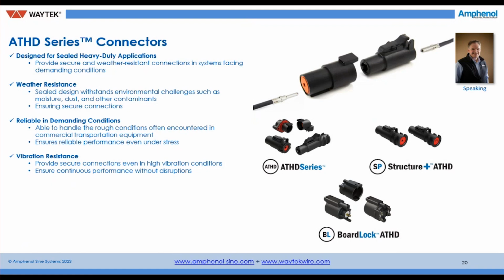And today, when we're developing connectors, the floor is IP68 and IP69K and even IP69K dynamic, where you actually have fluctuation or movement of the wires or the cables being introduced while you've got water ingress happening at the X, Y, and Z axis. But this is our ATHD series. Again, another key connector that can be found in many automotive and transportation settings.